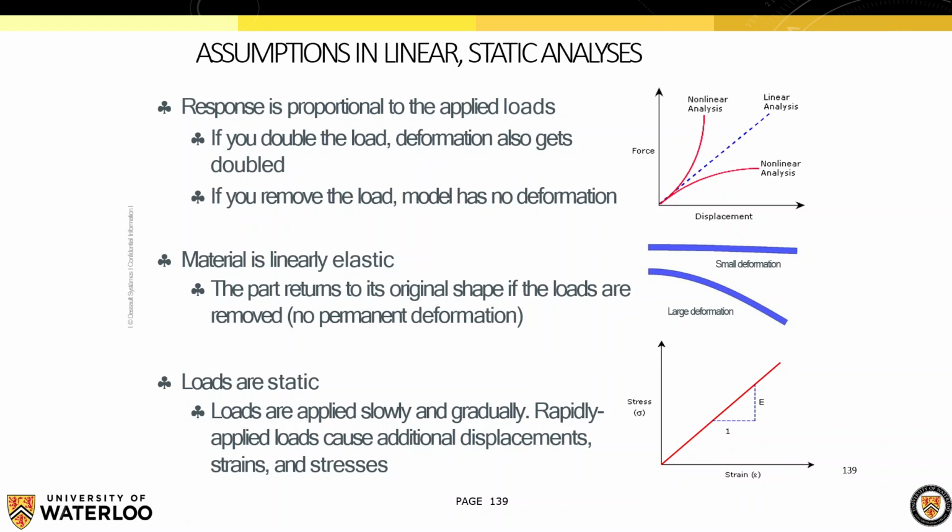displacements. Do you really want to do a static linear analysis, or do you want to do a dynamic nonlinear analysis? Is this really what you intended to do? And then you say, oh, yes, actually, I didn't know that the displacements were going to be that large. I should do a nonlinear analysis. Or oops, I made a mistake. I put plastic in as the material. Let me fix that. And now it's just a typical linear thing.